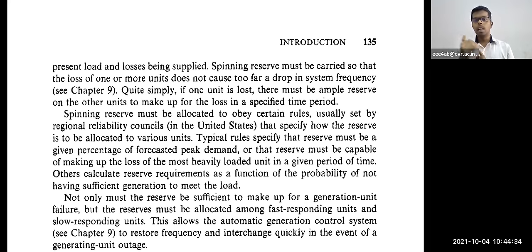In one line it is coming around 800 megawatt, and in another line 200 megawatt is lost to the fault. So you need to manage that 200 megawatt. Say in the ring connected system you get another 180 megawatt, and the other 20 megawatt is the deficit. But whatever fault happened can be rectified within a few minutes, and in those few minutes they have to give a reliable supply.